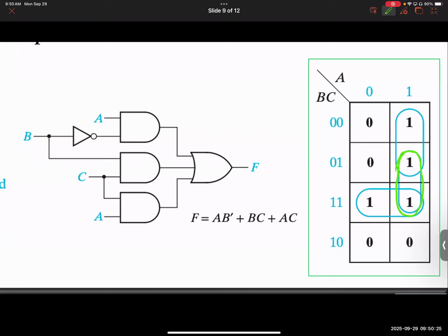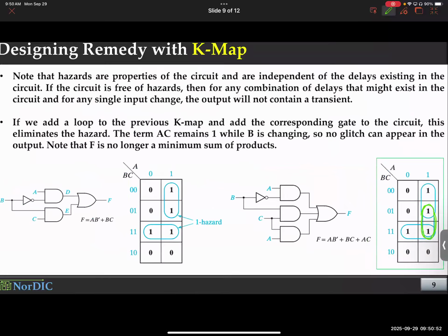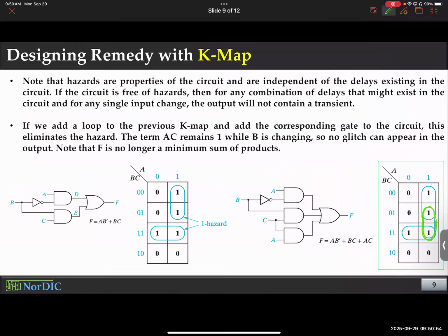We looked at the absolute optimization where you minimize using K-map and we ignored everything else. Now, as we see more and more issues, remember when we looked at multi-output gates, we sacrificed the functional output to group them in a way that you can share the logic gates. So that's an additional strategy. Now we're looking at taking up extra groups than necessary. If you add this extra group, I'm not going to go through this in class. You can look it up at home. Go through the exact same exercise.